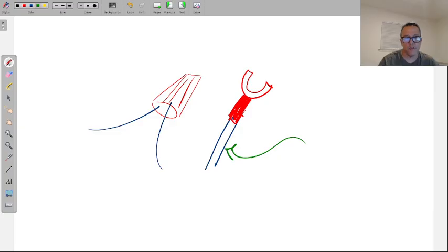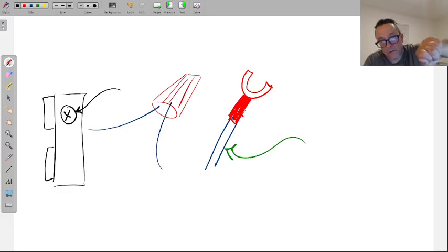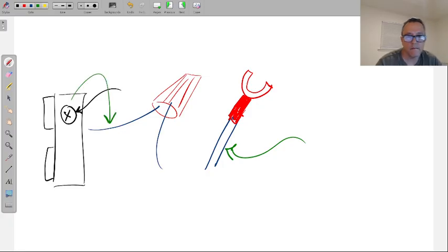So all the terminations, anywhere where you bring a wire in, the outlet, the side of an outlet, here's our outlet, the little side where we have the screw, that screw right there that you're about to terminate a wire to has a temperature rating. And that temperature rating has to match the one on the wire. Or the wire can be greater than that, but in no case shall the wire's temperature rating be less than whatever termination point rating that we're going into.